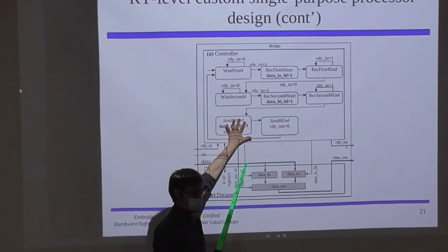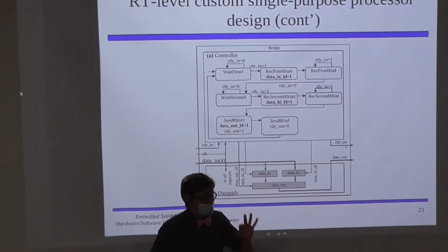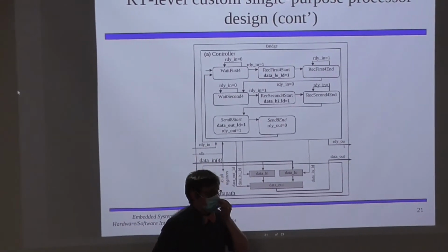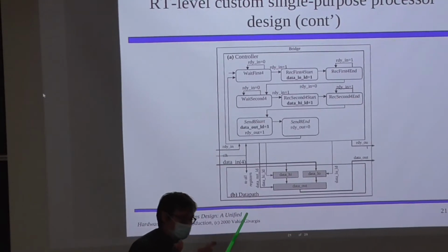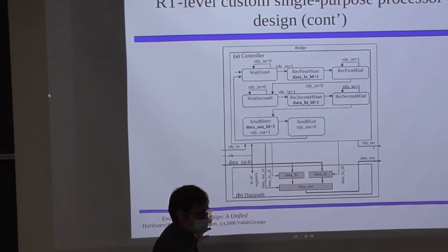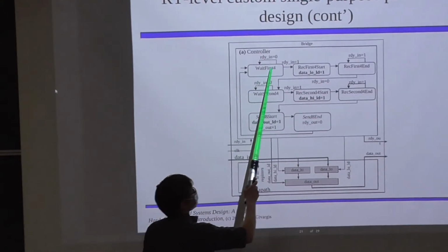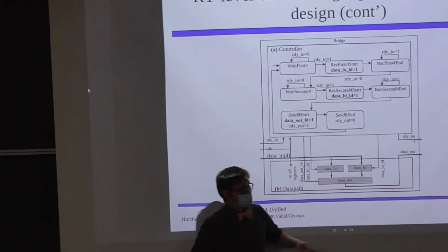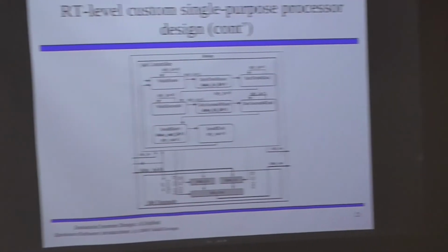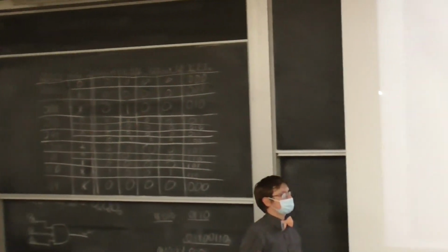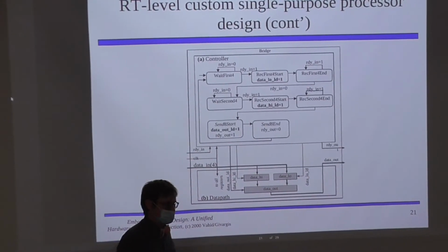Part of the optimization that we're going to talk about with these types of diagrams is that anytime you have a state that flows directly into the next state with no condition on the transition, that's a redundant state, right? And from an electronics perspective, yes, you absolutely could, as soon as you set the state to this state, put that high as well, right? I'm not claiming that this is a fully optimized design. So it's more or less that one doesn't matter, so we can just put it as 0 in the table?